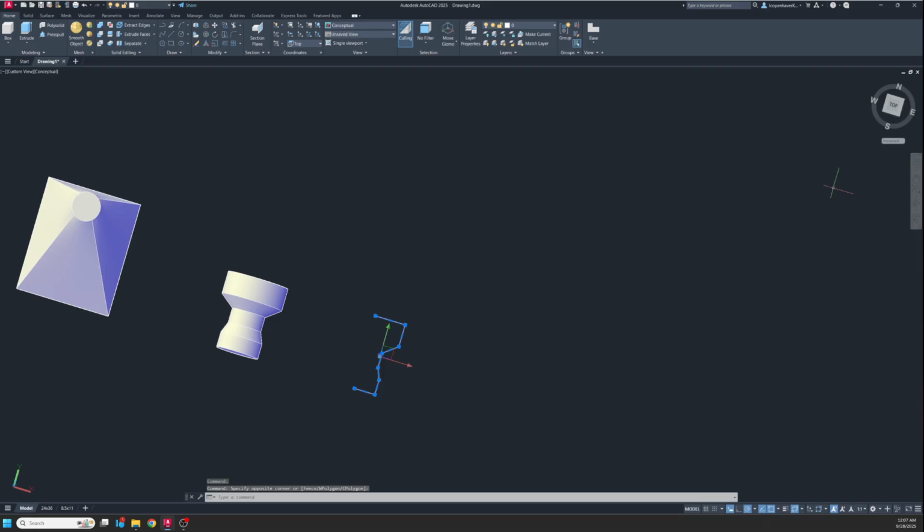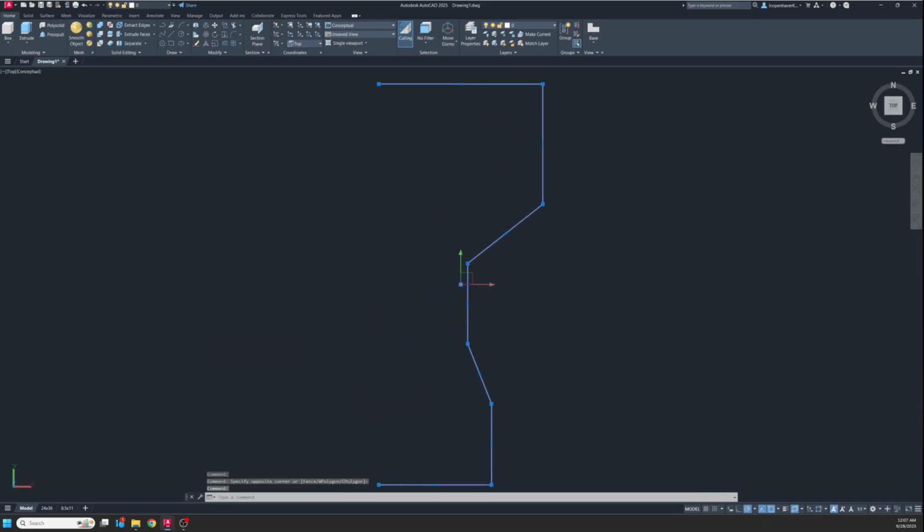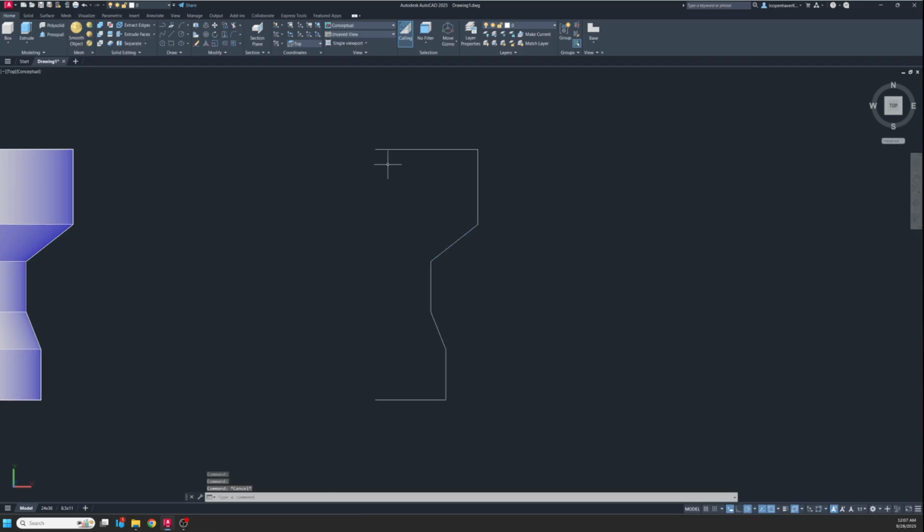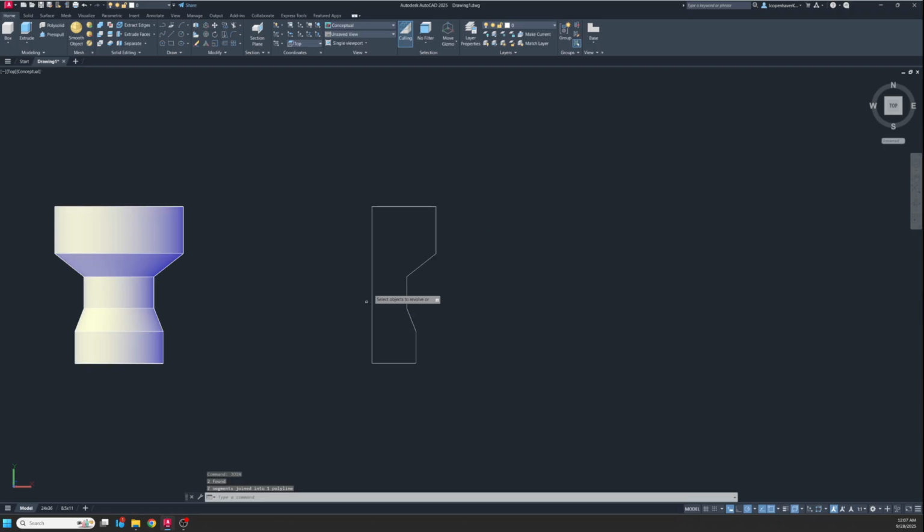You can also do this where the axis is not actually connected to this shape, so then that'll give you something with a hole in the middle. So let me close that. Let me join all those, and I'm going to type my Revolve command again. Select the object I'm going to revolve, and then I'm going to start that axis some distance off of the thing.